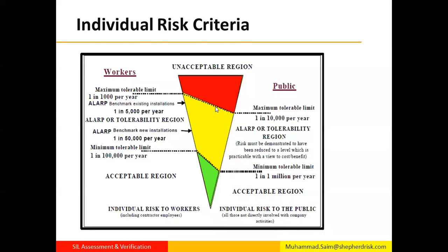One of the questions is, what is the minimum and maximum test interval period? We set the test interval based on the PFD calculations. As long as we achieve the target PFD set by the risk analysis, we can even set up a test interval of 20 years. Sounds ridiculous, but if the calculation says so, okay, fine, well and good.